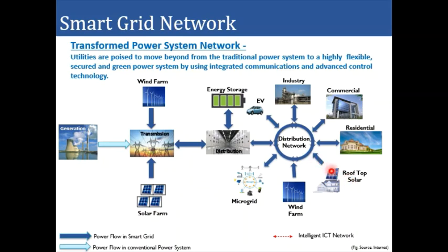Solar power is generated when the sun is there, but suddenly if you have cloud cover, the solar power reduces to zero. Similarly, in case of a wind farm, when wind is blowing, you get the power, but if wind stops, the power output also stops. So those intermittencies which are now being integrated into the distribution system create a challenge on how to monitor and control the distribution network.